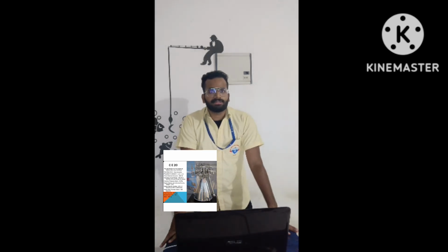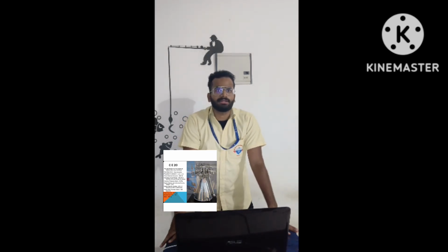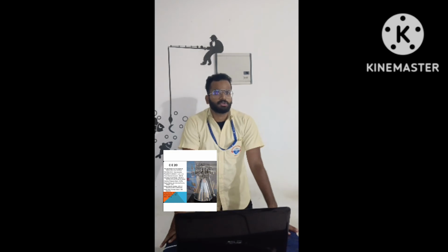Engine burn duration 595 seconds. Total flow rate 62 kg per second. Nozzle area ratio 100. Mass 588 kg.